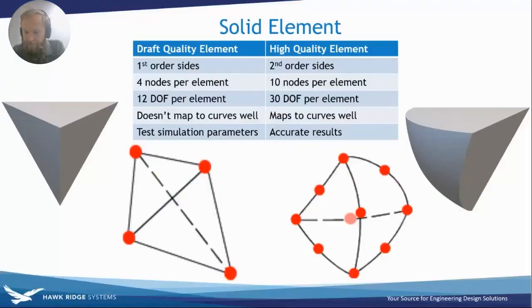When would you use P versus H? Honestly, I kind of use them both. What I'll do is an H adaptive to get my mesh looking dense in areas. And then if I'm finding my degrees of freedom are getting too long, then I'll change the quality as well. I'll start off with the H adaptive because it's way easier for me to visualize and I can see what's going on more.